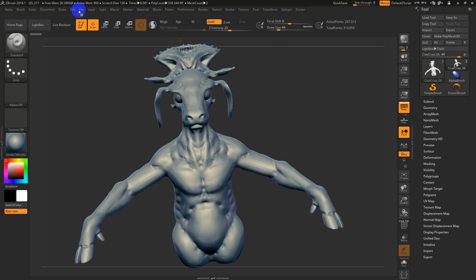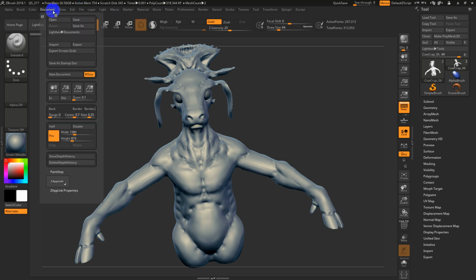Now if you do go to File, Save As, this is the ZBrush project. Again, I think I brought this up last class, but it's important to remember that this will save virtually every setting throughout the software, and by default this undo history is on, and ZBrush has unlimited history, unlimited undos. So you could have thousands and thousands of actions stored in your file, which can make it very, very heavy and very slow. It's one of the main reasons I don't use this, even though I can turn it off. Also, if you have a bunch of tools stored in the palette here, that actually gets saved off in the document, which is through File. Sorry, Project. Document is another thing.